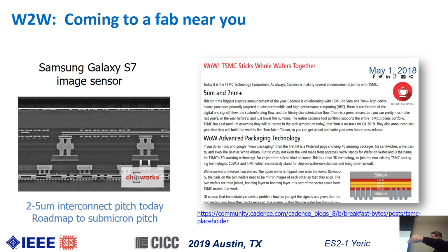The cost and functionality reason for the cameras is this, and they're not quite there yet, but to get to a per-pixel stack of sensor, memory, and logic. And that will give them a huge advantage. You're starting to see some products, like there's a 1,000 frame per second camera, I think, on the new Apple phone. A lot of it has to do with the fact that you can put memory right under the pixels of the sensors. There are really impressive wafer stacking machines that have been built to do this, and the logic fabs are starting to buy these machines. So you can just see this wave coming over to logic soon.